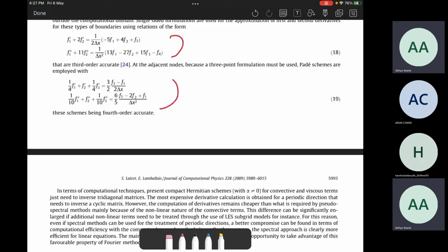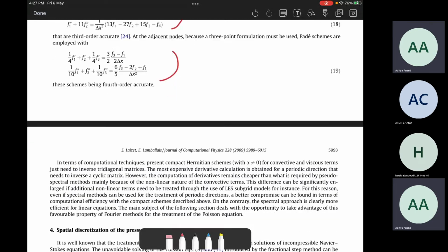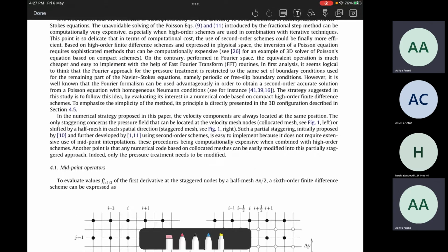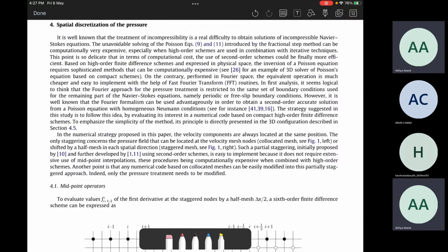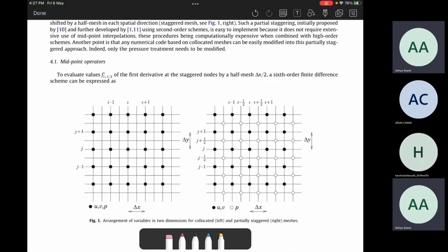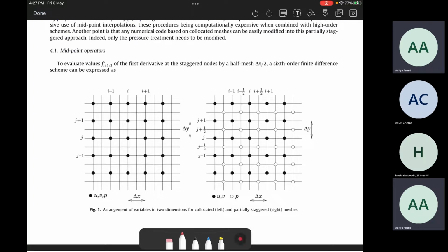Yeah. So for the pressure, they have used a staggered grid. Let's say this is the computational grid. They solve for pressure on the staggered grid, as marked by red by me, on the right hand side. It is these hollow circles. So it solves for pressure here.